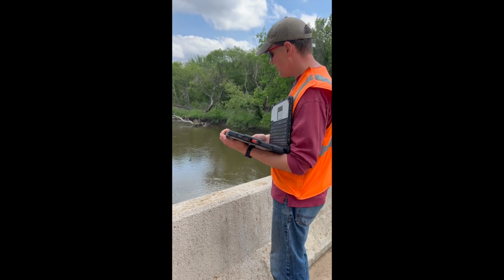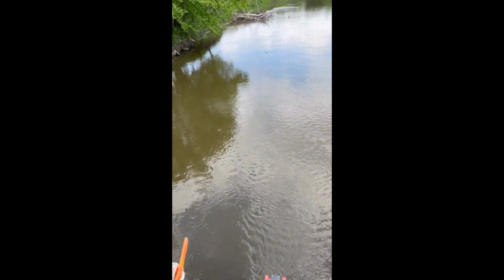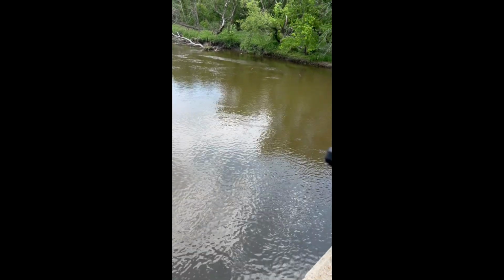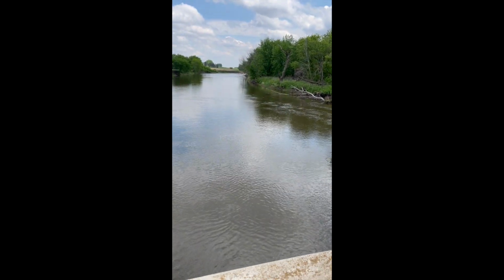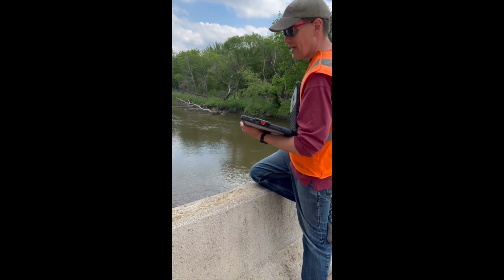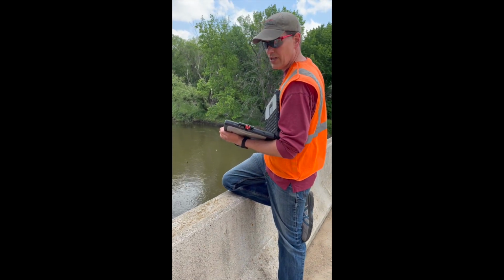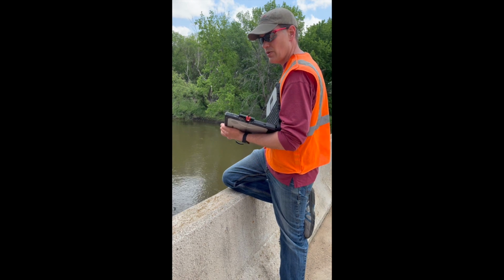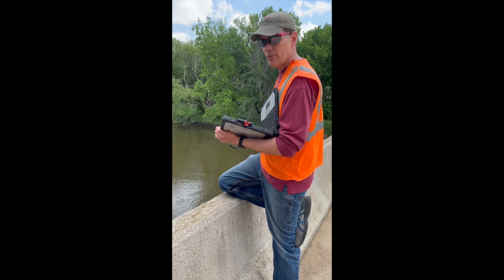All right, we've moved to a new location to take another bed test. This is halfway in between where we would assume the most bed movement is at the highest rate of discharge to right in the middle between low discharge and high discharge. So we can get a moving bed here. Then we will move to the other side, right in between the high and low, and we'll go take another discharge there. We need just 3 for the calculations, and it will figure out the rest.